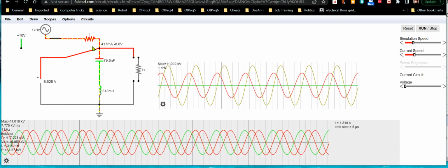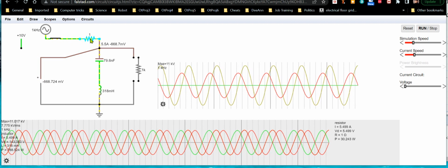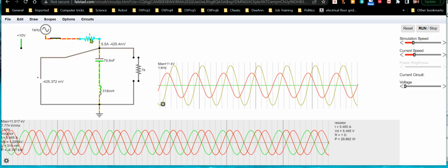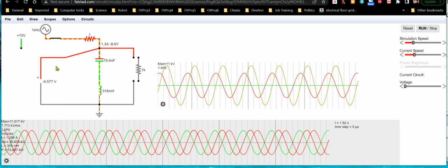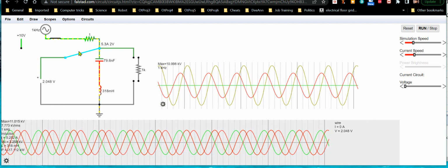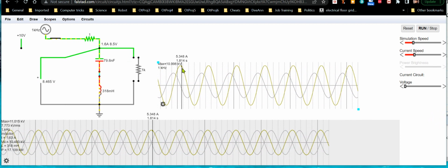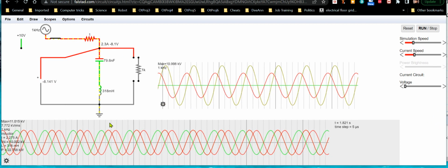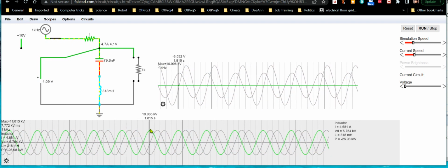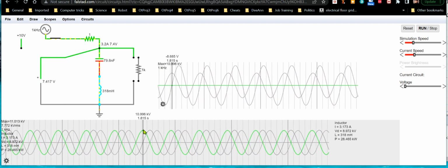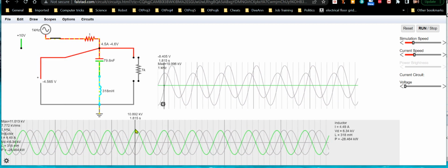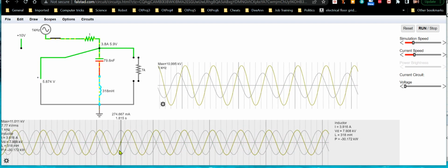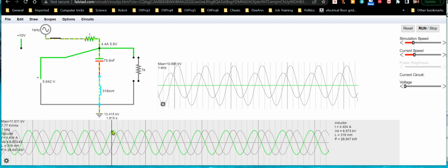And that's because we're at resonance. In other words, in theory, all the voltage is probably across the resistor here on average, but not continuously, because there is a voltage there, and again it's peaking out like 10 point something kilovolts. So across any given component, the capacitor's got 10 kilovolts across it, and the inductor's got 10 kilovolts across it, but they're 180 degrees out of phase.